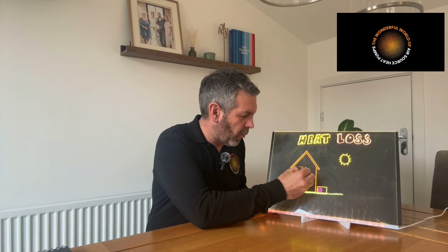So if you look at the diagram behind me, what we will try to create is a comfortable environment in the home of, let's say, 21 degrees for a living room. And we want to be able to achieve that when it is the worst conditions outside, our design outdoor temperature. Now for Scotland, that is -5 degrees. So this gives us a baseline, something that we are going to design to.